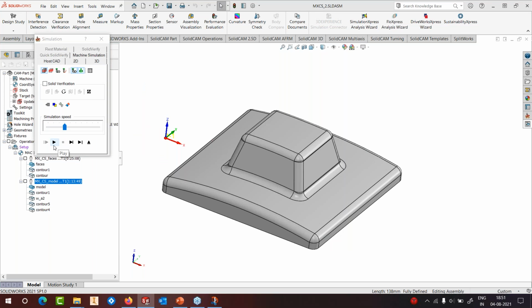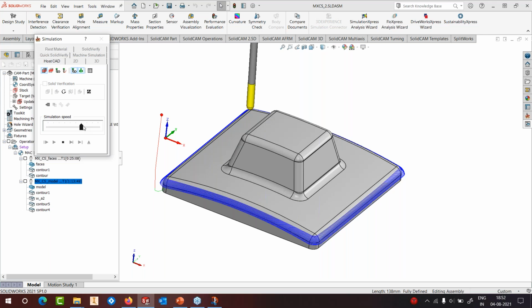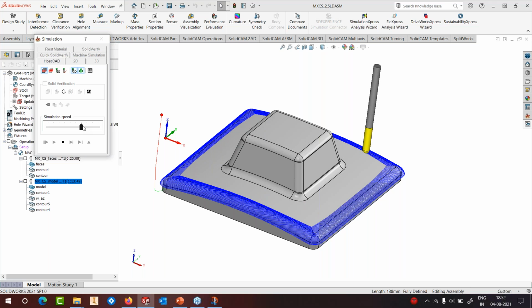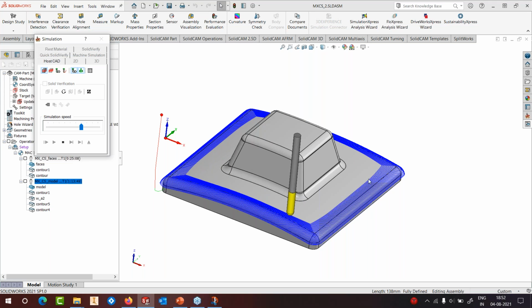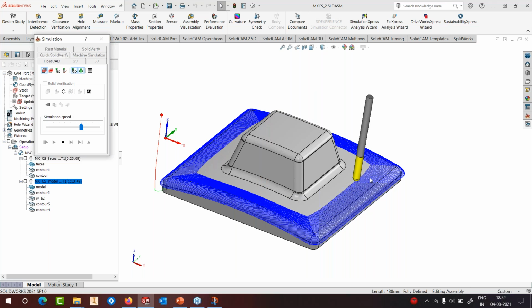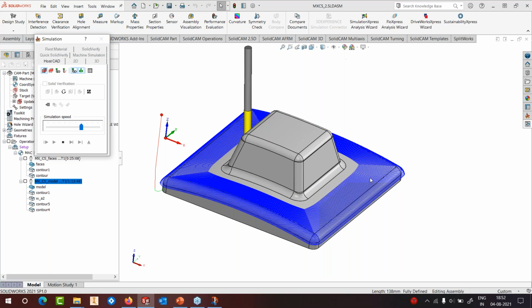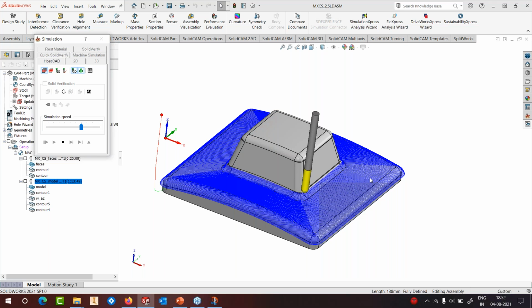And here, like I said, it won't look from the direction of the tool axis, but it will use its own intelligence to determine a constant step over across the entire surfaces that it's going to machine. So this is how it's going to look like. You can see it doesn't matter where it is machining, the pattern is consistent. The slices have the same passes or the same step over. The maximum step over it is using here is 0.5 millimeter.